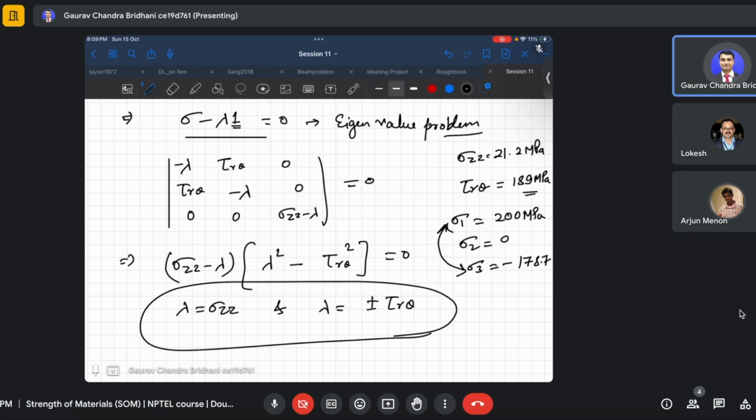Yeah, so you can't take a ratio of squares. Factor of safety is actually the ratio of sigmas. So you have to take the ratio of sigmas, not the squares. Because here the yield criterion is defined in squares. In Tresca, it is not like that. It is sigma max minus sigma min divided by 2, which is tau max, less than or equal to sigma y by 2. So there it is a simple ratio, but always the factor of safety is the ratio of the stresses, not the square of the stresses.